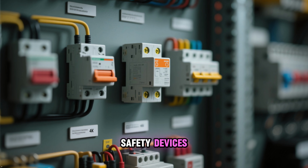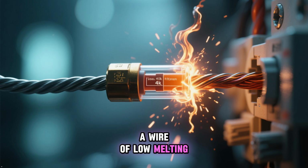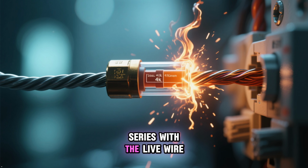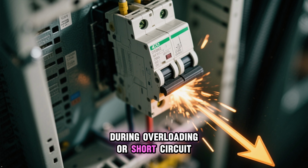Safety devices. Fuse: a safety device with a wire of low melting point and high resistance. It is always connected in series with the live wire. During overloading or short circuit, excess current heats and melts the fuse wire, breaking the circuit and protecting appliances. Circuit breaker, MCB: an automatic switch that turns off during overloading or short circuit.